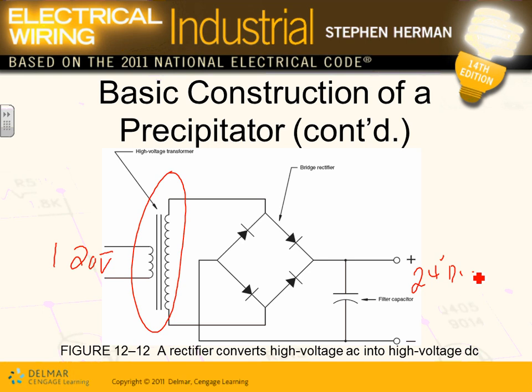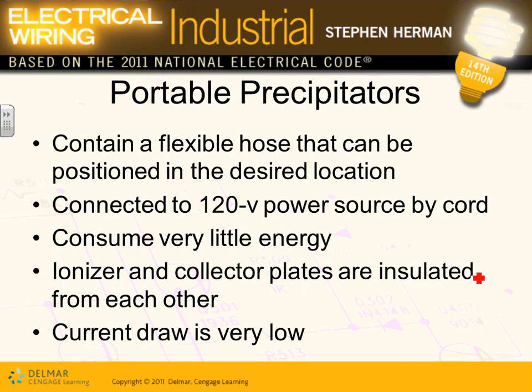Any comments, guys? The ionizer will be positive, the collector will be negative. You take the mist, positively charge it, you blow the air, push it through the collector, it gets attached to positive, attract negative, right? It attracts the negative and you collect the dust. That's how they do this system.